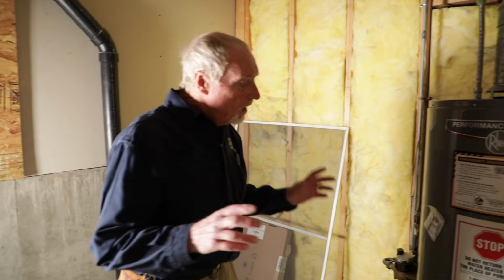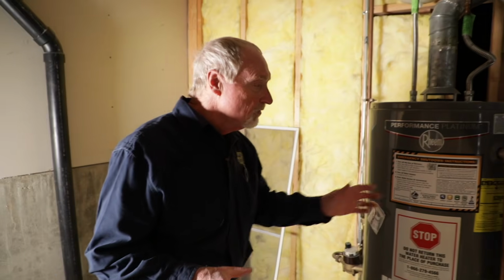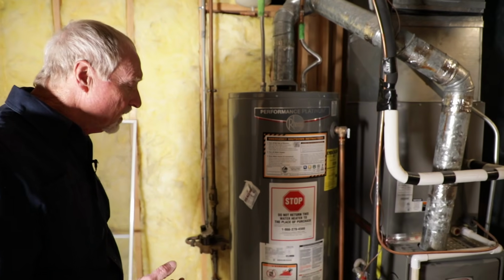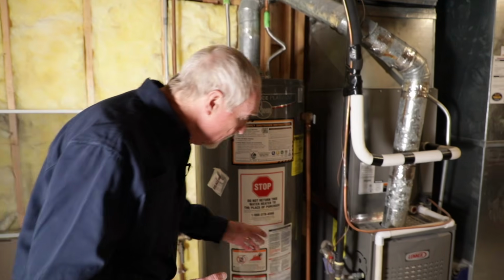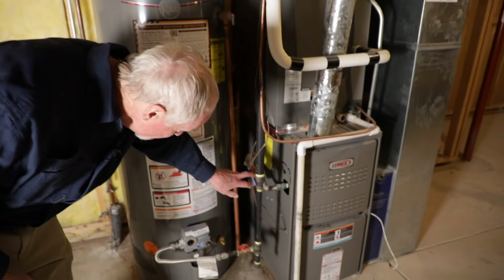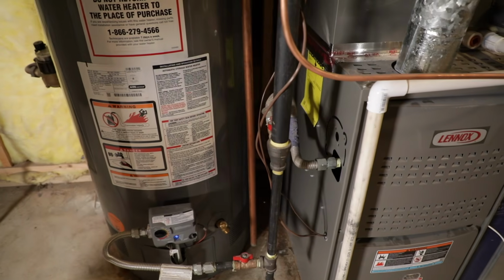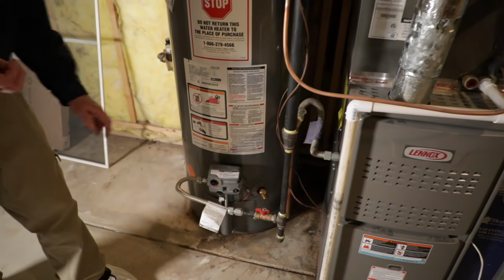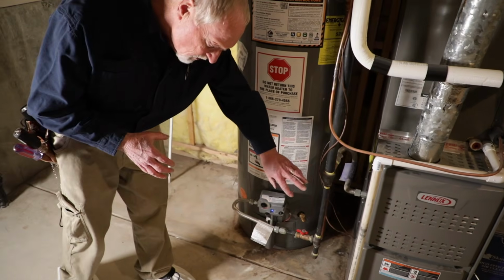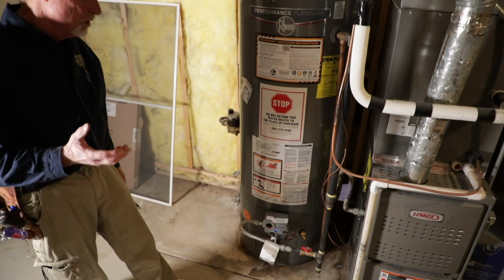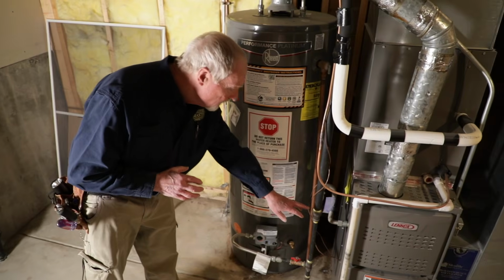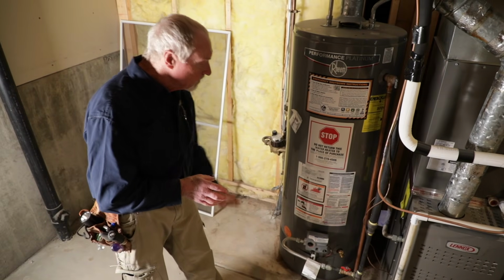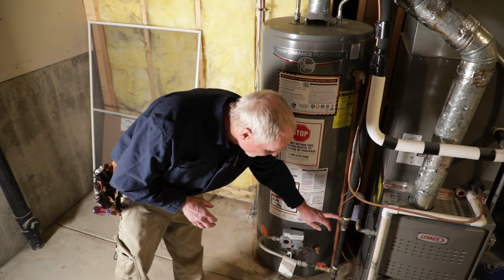So, also part of our plumbing is our gas line. In this case, we have a black pipe gas line coming in, and here you can see they used yellow Teflon tape on it, which is the correct kind of Teflon tape for gas connections, never white. Sometimes this comes in some other colors, blue is a popular color, but never white. White is only for water, gas deteriorates it. We're looking good here with our yellow Teflon tape.